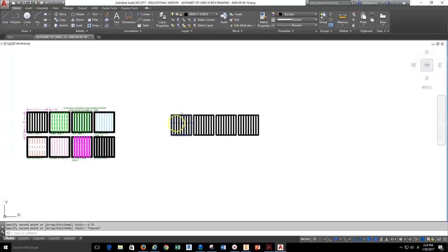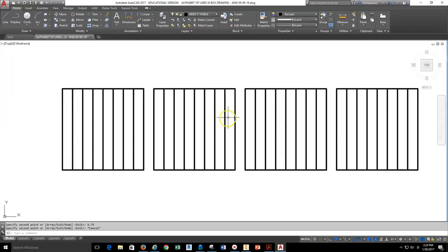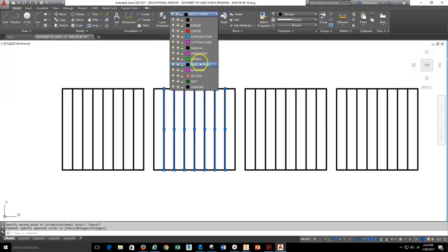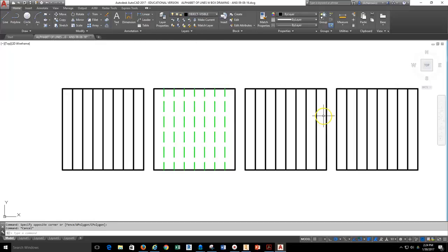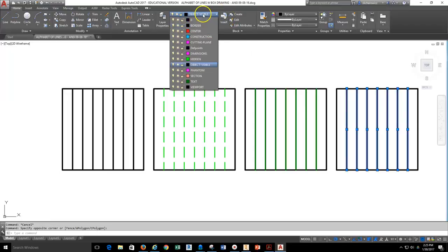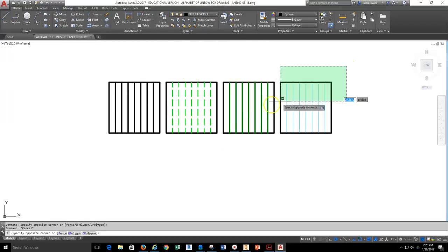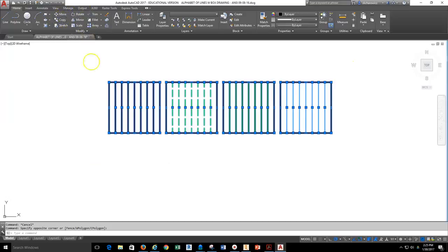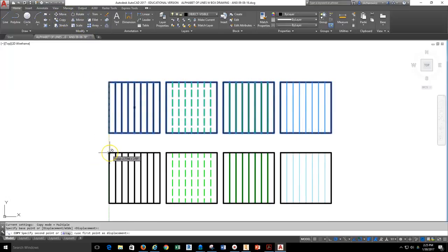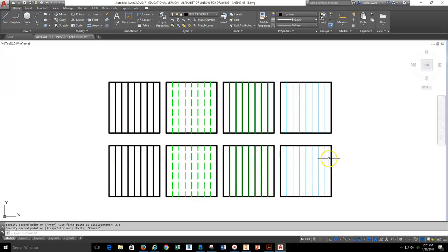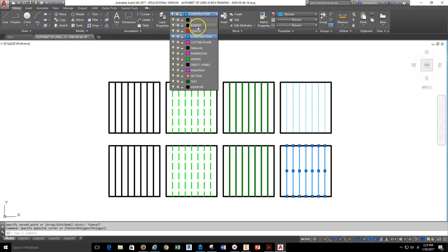Once I've set this up, I can go ahead and select with a panning window the hidden line and set up the hidden line style. I can then pull across this set of lines and set up the text line, and then I can set up the construction line. Very quickly and easy to make this drawing. All 4 boxes and lines can then be copied and moved down, creating a 2.5 displacement, and then moving through I can change all of the necessary lines to the proper line size as well.